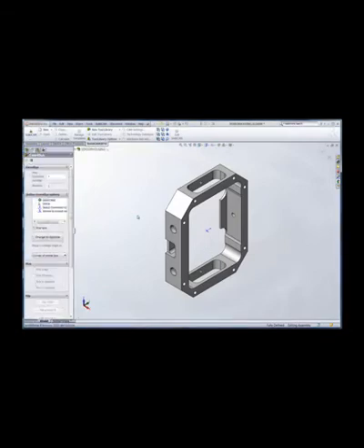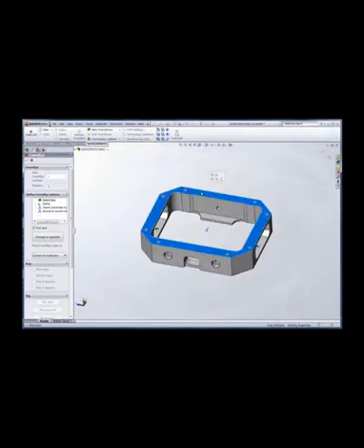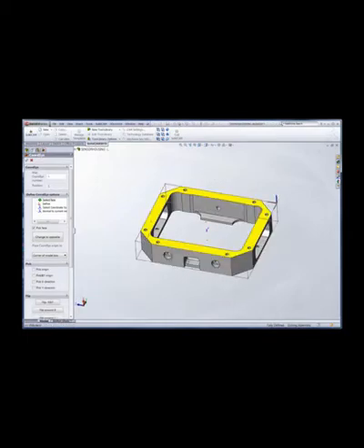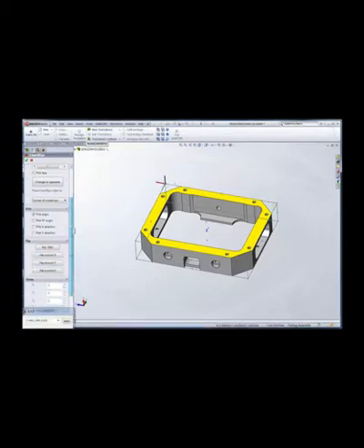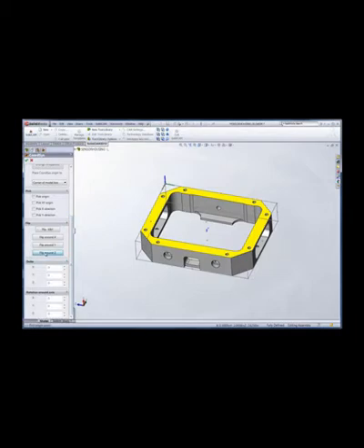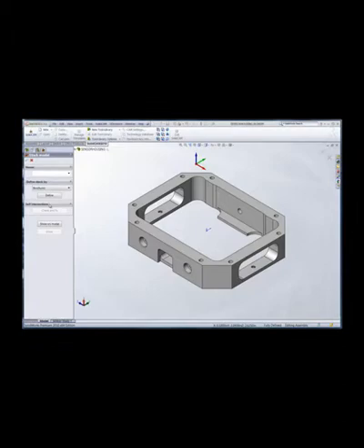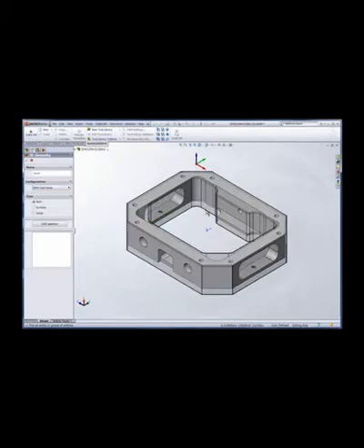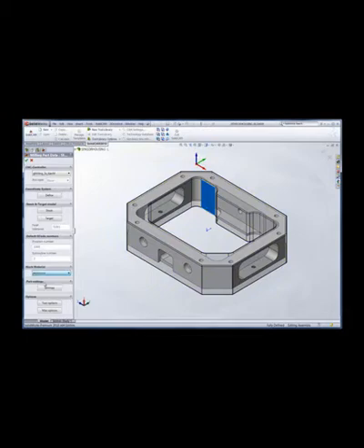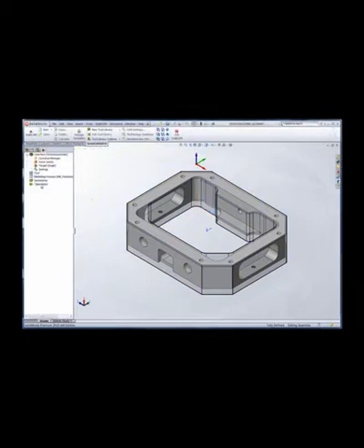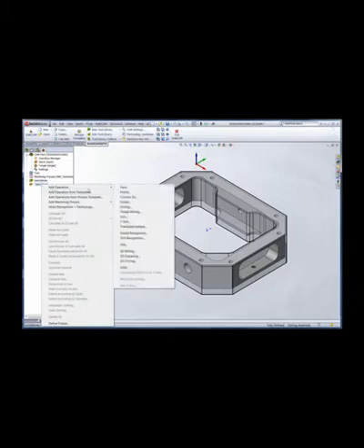We'll assign the coordinate system by simply selecting on the face that we want parallel with the XY axis. If we need to move the origin, you can simply pick a new location. There are also a number of methods for realigning the axes as necessary. Next, we will define the stock. We'll use 3D model in this example, and we'll define this from the available machine configurations using the casting stock. Next, we'll assign the work material, and we're ready to begin machining.